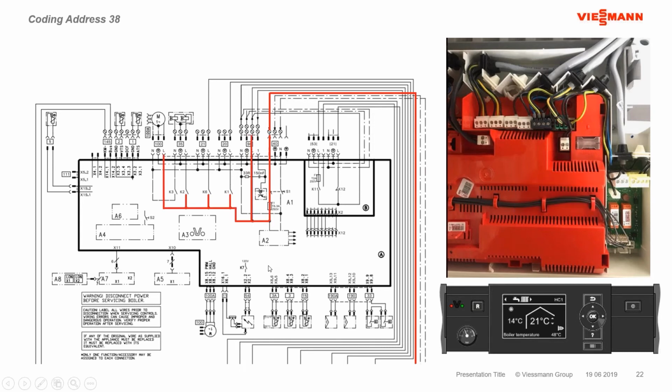Once it goes past the fuse, the line voltage is sitting here now on all of those controls for the burner, waiting for those relays to close on the call for heat to activate the burner operation. And it also tees off and goes to the 96 plug, just like the neutral did. And again, branches off at the 96 plug. We're going to go past that little branch. We'll come back to it.